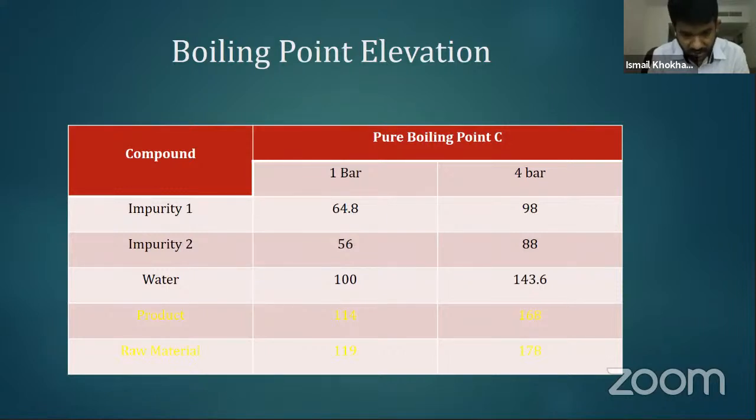Either you use an oil system, it's fine, it can work at atmospheric pressure. But if you use a high pressure steam like 10 bar steam, then again you require a jacket to handle that pressure. So it was becoming quite risky, but since we had a target to achieve this distillation in a single distillation column, it was a matter of concern how this high pressure is going to impact the fabrication designing.